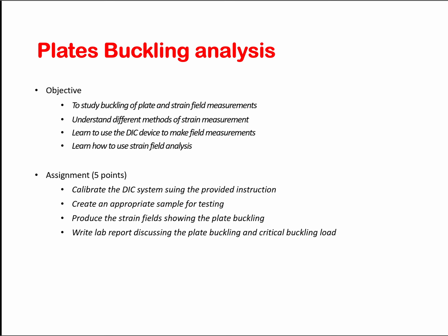In your lab reports, you don't have to do any calculations, but the idea is for you to calibrate the DIC system using the provided instructions, to create an appropriate sample for testing and to produce the strain field showing the plate buckling, and eventually to summarize all of this in your lab report and discuss how you think we should measure the critical load of buckling for a plate.